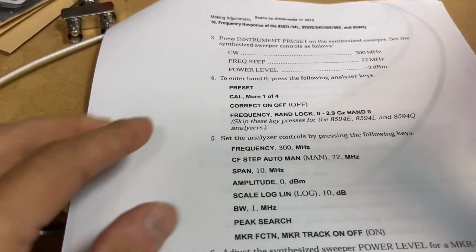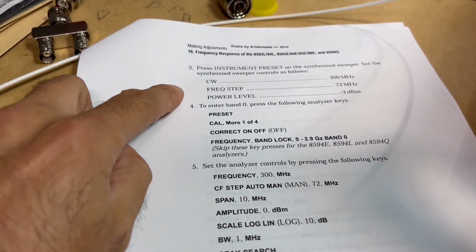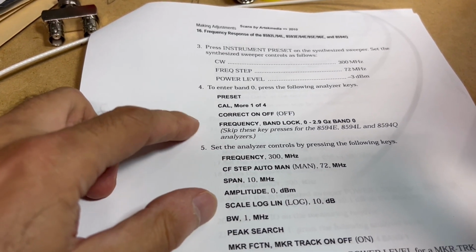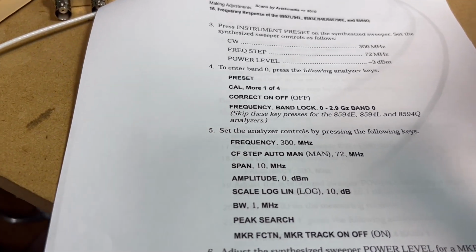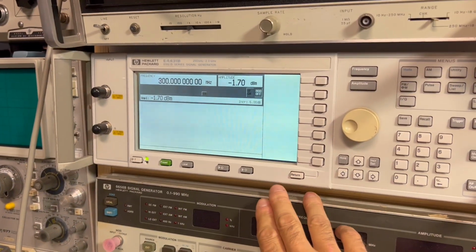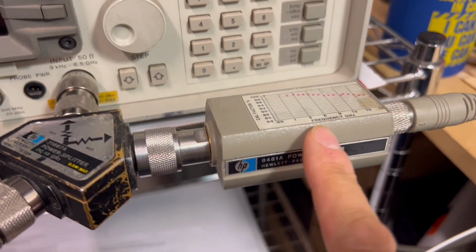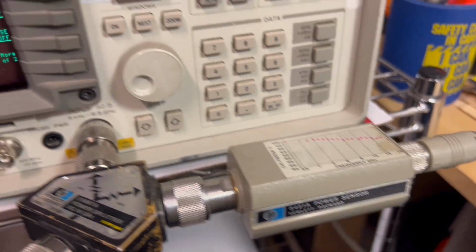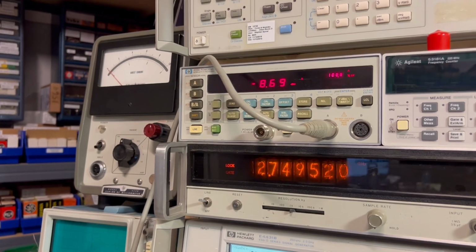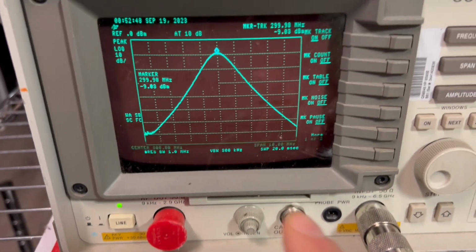So first thing we're going to do is jump back into the section here before we did the band 0 adjustment, and we'll set up our spectrum analyzer for the 300 megahertz, basically our base measurement for taking our relative readings. And I've done that already, and I've got the equipment hooked up here, so you see that I'm feeding in the 300 megahertz source here through this power splitter, going to a power sensor here using the 8481 power sensor now this time. And we got our power meter set up here, and we're going to take our relative, so we're going to put this in relative mode here.